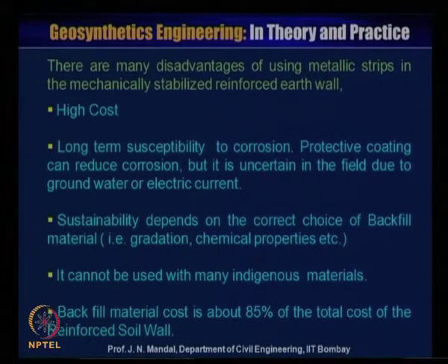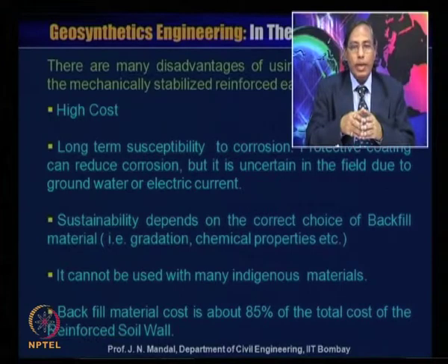There are many disadvantages of using the metallic strip in mechanically stabilized reinforced earth walls. These include high cost and long-term susceptibility to corrosion. A protective coating can reduce the corrosion, but it is uncertain in the field due to groundwater or electric current.